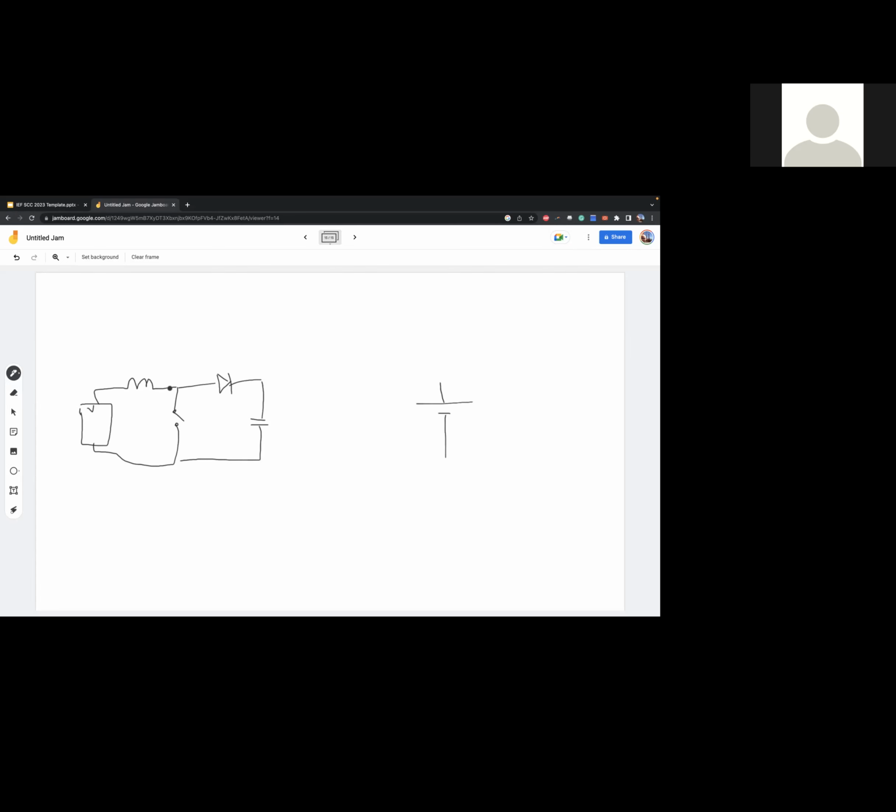And then the battery management system has a switch that disconnects the battery from the MPPT once it's fully charged. Well, you wouldn't want that, but if you reach an overcharge state because you didn't set up your power tracker to the right charge termination, that could occur.